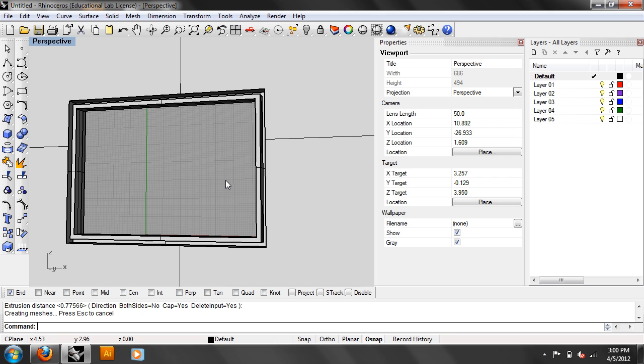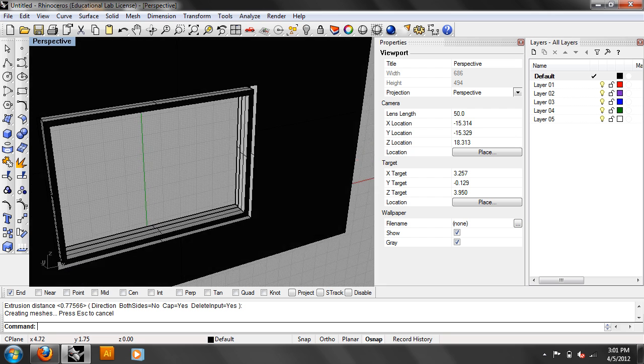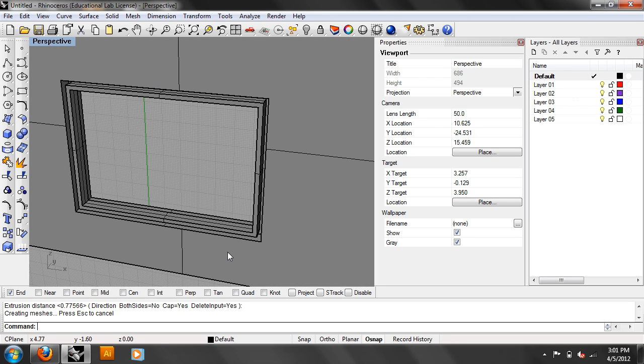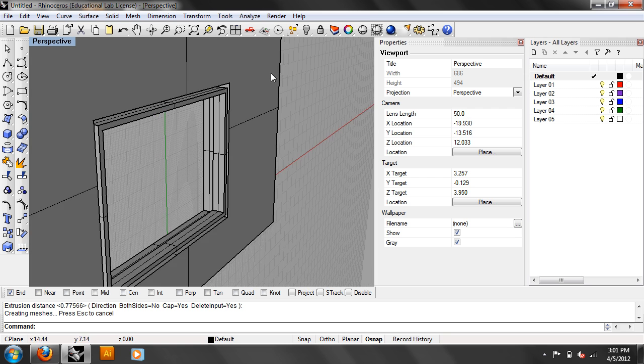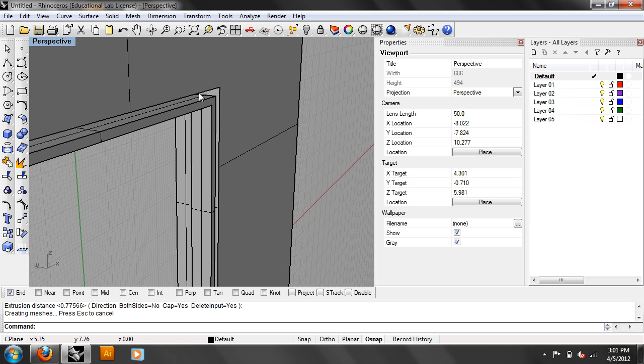Oh, you can get reveals. So you have a gap between things, so pay attention to those. Those are also another source of shadow, right? So you have the gaps between panels of things. If you actually have a reveal behind you on the sides of your mullion, some of you guys have these, okay? So you can extrude in the negative, or you can start that extrusion halfway, whatever that is, if it's only an inch reveal, but you can get those reveals in your geometry.